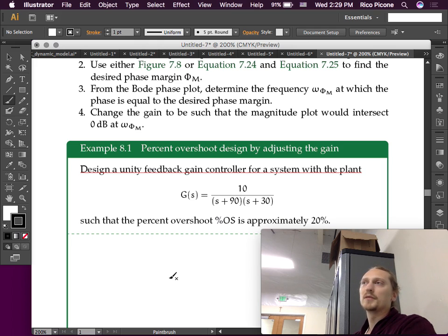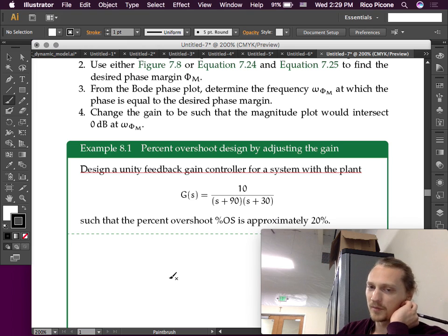So that's a really small DC gain. But it does have this gain term of 10 in the numerator that we need to watch out for. Sometimes when we refer to the gain of a transfer function, we're referring to that DC gain value. Sometimes we're referring to whatever that numerator is. It just depends on the context. We just have to be aware of the two possibilities.